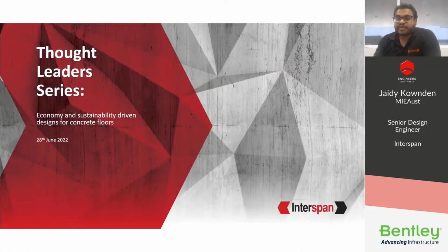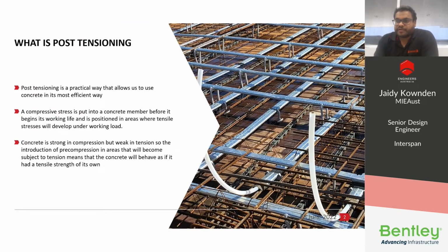Thank you for the introduction, Amanda, and thank you to Engineers Australia for giving us the opportunity to do this discussion on post-tension slab. So firstly, we'll have an introduction of post-tension slab, what they are, how they work, and why we use them. Post-tensioning is a practical way that allows us to use concrete in a more efficient way. Compressive stress is put into the concrete member through the tendon before it begins its working life and is positioned in areas where tensile stress will develop under working loads.